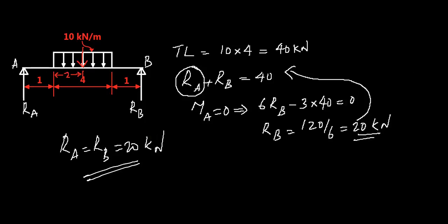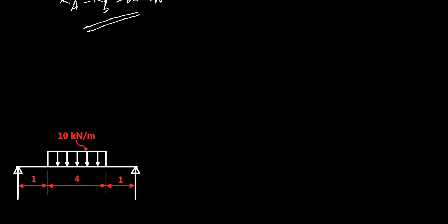Now to calculate the bending moment, we use the method of sections. So you take the first section between point 1 and 2. So you have point 1 here, 2. So your first section will be here. You have a section XX, reaction Rb, distance x. So moment about the section, you always take moment about this point.